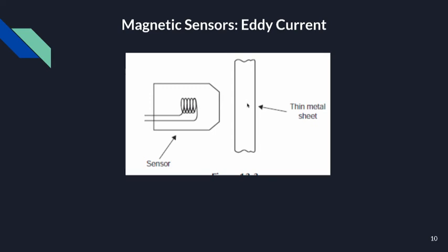This allows the sensor to measure the displacement of very thin targets, such as the steel diaphragm of a pressure sensor. The eddy currents alter the inductance of the probe coil, and this change can be translated into a DC voltage output that is proportional to the distance between the probe and the target. Measurement resolution as high as 0.1 millimeter can be achieved. The sensor can also work with a non-conductive target if a piece of aluminum tape is fastened to the target.